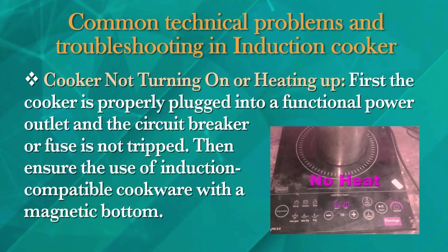If the induction cooker is not turning on or the cooktop is not heating up, first check the cooker is properly plugged into a functional power outlet and the circuit breaker or fuse is not tripped. Then ensure the use of induction compatible cookware with a magnetic bottom.